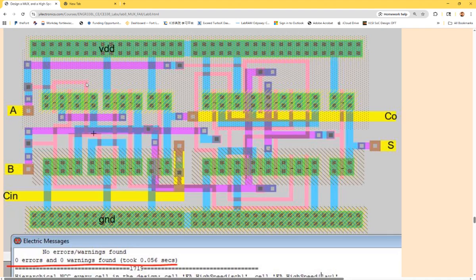But if you use poly to make a connection, what's the problem? It has resistance between the gates, and there will be a voltage drop, right? So in that case, it's not ideal. But it's super short. It's probably fine. I'll just directly use poly to make the connection. Like this case, okay? This case.